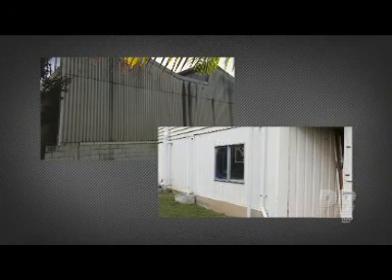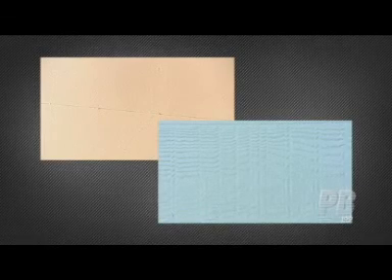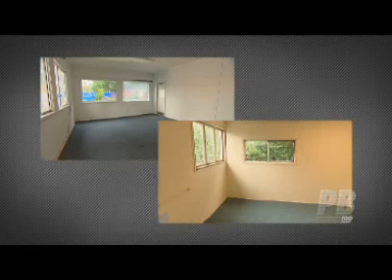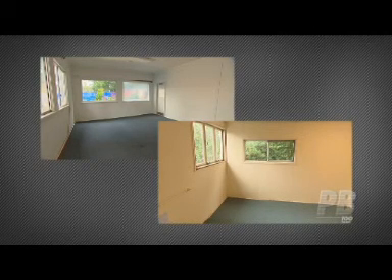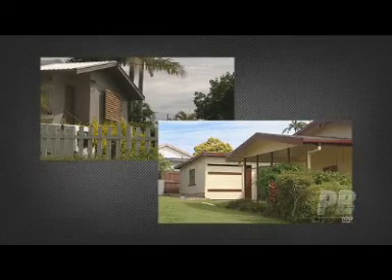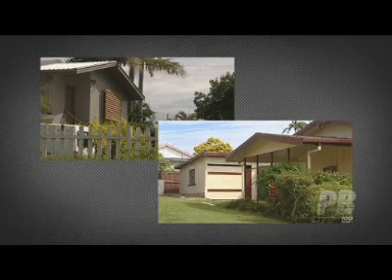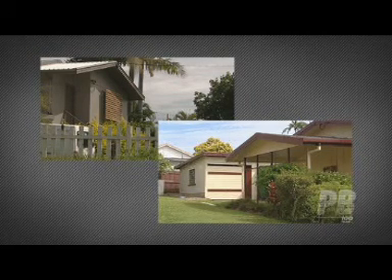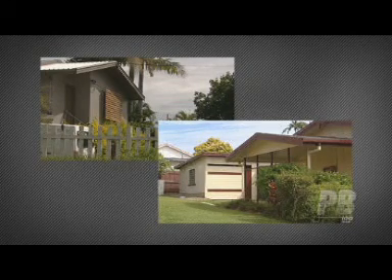For example, you might want to know about the makeup of different walls of a building, where one is corrugated and the other shadow line. There could be a difference in surface finish. Some AC sheet has a bubble texture, while other types are smooth. Sheets in different areas may look different because of discoloration due to age or wear. Location can also be a factor. An older building may contain AC sheeting, while extensions or the surrounds of newly added windows or doors might have non-AC material.